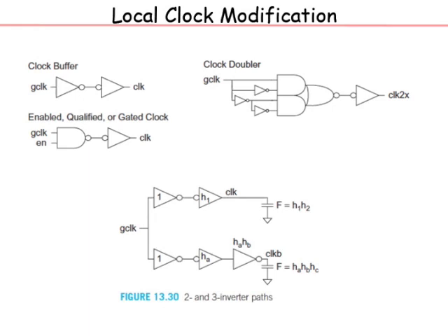So you can do something similar out here, where when the global clock goes high there is a pull-down here and a pull-up here. Similarly, there is a pull-down, pull-up and pull-down here. So 2 pull-downs plus 1 pull-up has to match 1 pull-up and 1 pull-down. And that you can set up as equations, and based on the loading you can go back and calculate the sizing and so on, and get the delays to be the same.